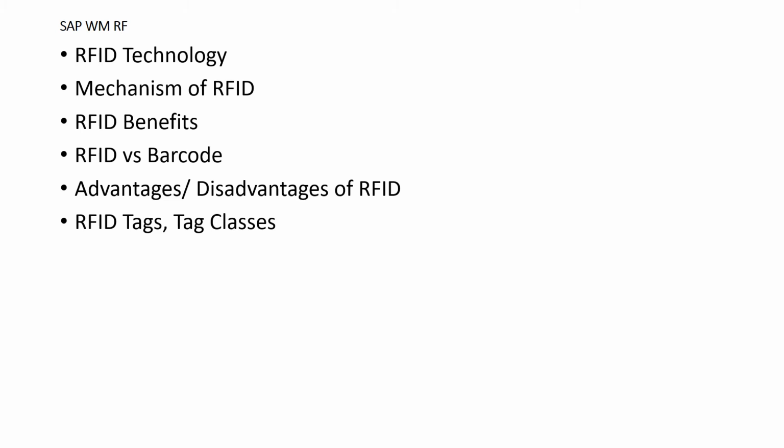If the pallet was full of mixed products, the large number of RFID tags can be read almost instantaneously. The tags would be read sequentially, not simultaneously, but the reading could still be completed in microseconds. The data on the RFID tag can be changed or added to as a tag passes through specific operations. Read-only tags are less expensive than read-write tags.